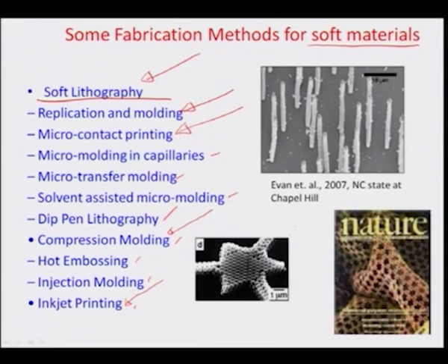These are some examples of what can be done with polymer MEMS. For example, this is an illustration of how PDMS doped with Fe2O3 particles can be used to make these high aspect ratio structures. These structures must be close to 20-30 microns high and maybe about 2 microns in diameter, and these can be used as tentacles. Just because they have Fe2O3, an external magnetic field tends to move them, and they can be used for pedaling action, which can move forward the organism which possesses these tentacles.